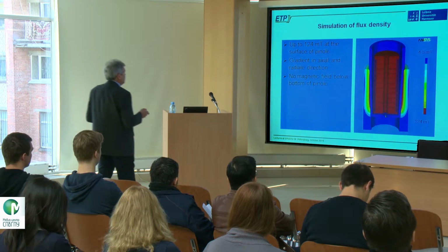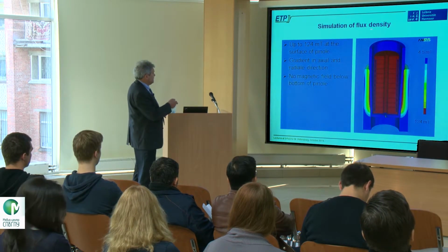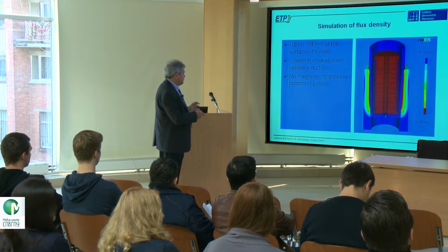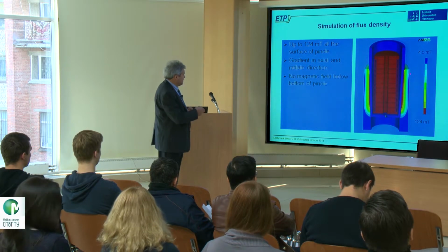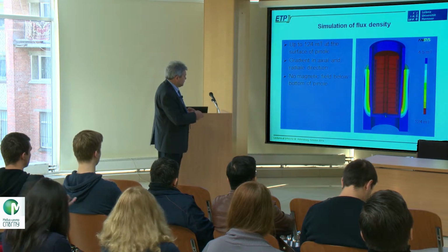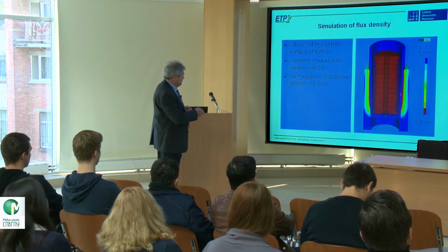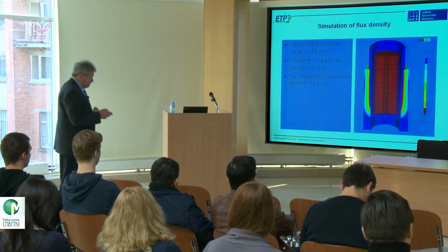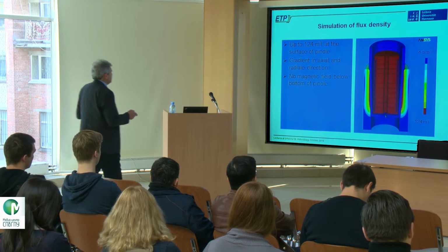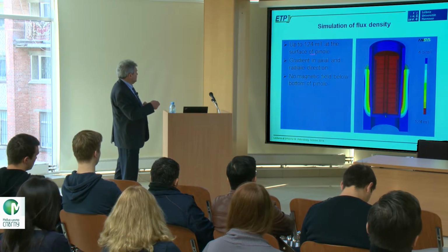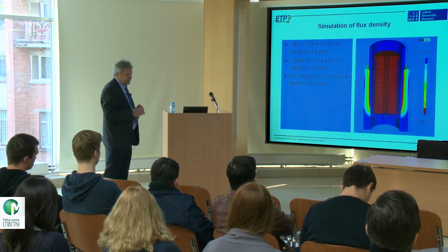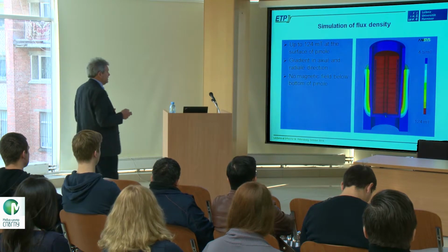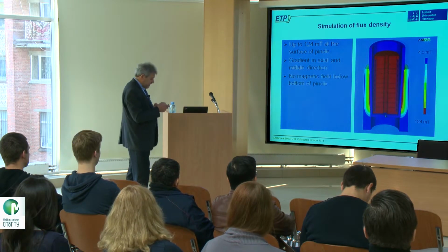We have done a simulation of flux density to check how much flux still comes to the melt. You see here it's big. Of course, you have some end effects here, and also some top effects, which have to be investigated. The flux density was not very high, 124 millitesla. Quite low, but enough to realize this effect.